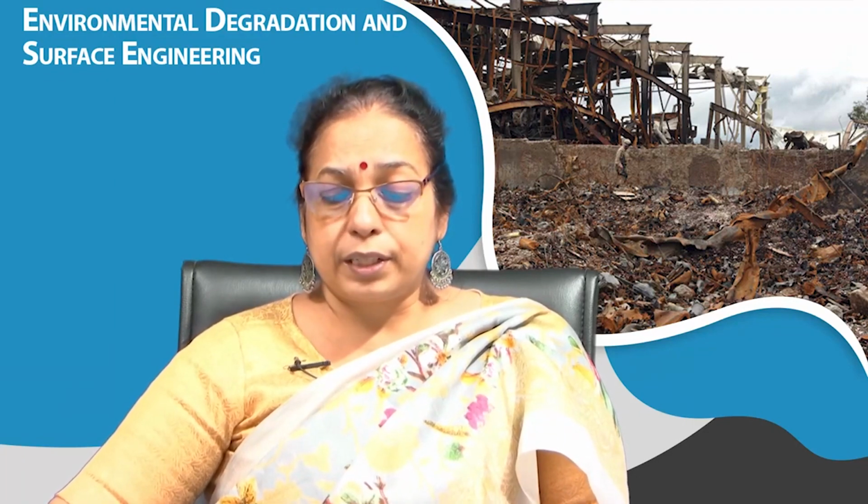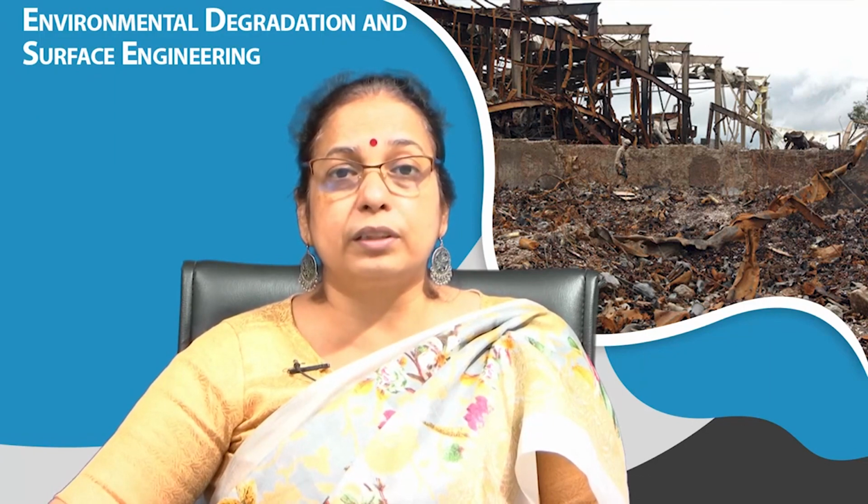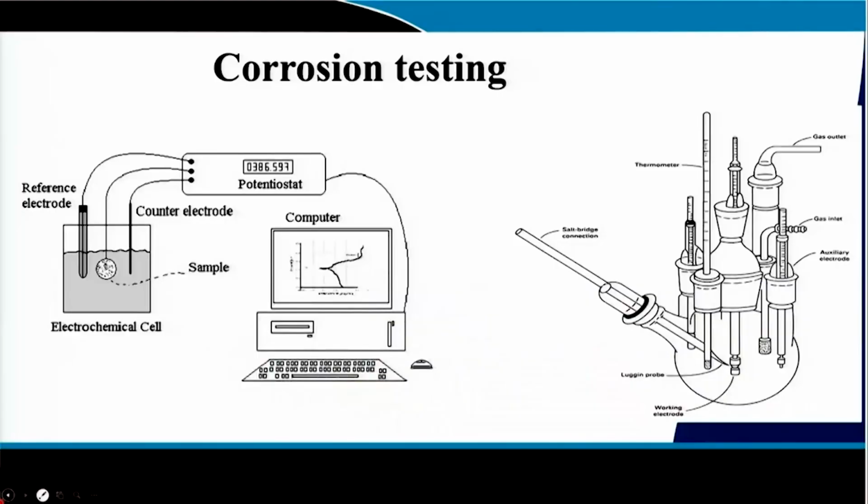Now, I would like to describe a few tests which are applied for knowing the electrochemical corrosion behavior of the component in aqueous solution. One of the important and very widely used techniques for corrosion testing of the component in an aqueous environment is the potentiostatic polarization technique. What you do is that you polarize the component.